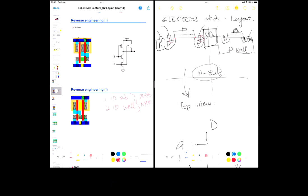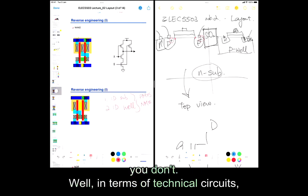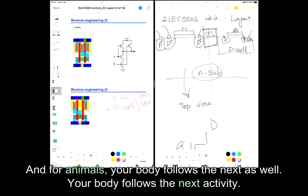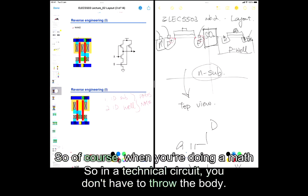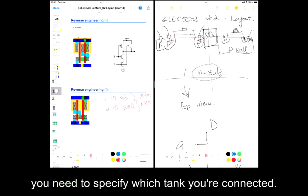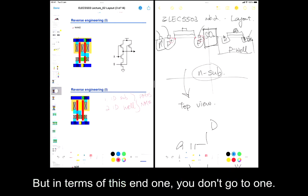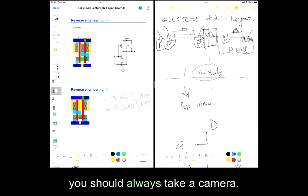Another very good question: do you have to draw the body? What do you think? In terms of digital circuits, you don't need to draw the body, because the body for PMOS is always connected to VDD, and for NMOS the body is always connected to ground. So in a digital circuit, you don't have to draw the body. Of course, when you're doing a lab project, in the simulator itself, you need to specify which potential it connects to. But in terms of these answers, you don't draw the body. It won't be wrong, but the body you draw is usually only for memory. So it's not necessary.